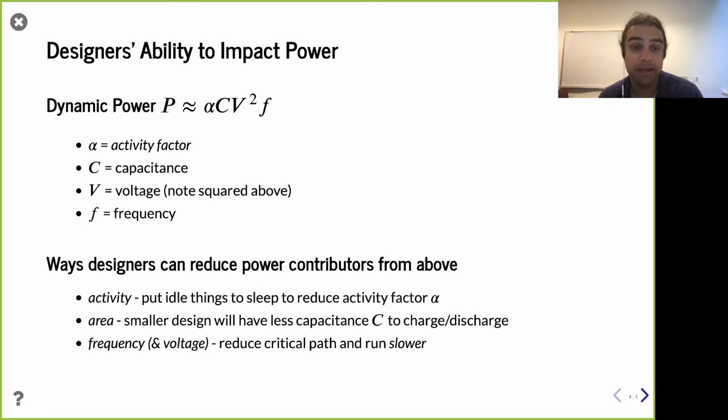And actually, well, the lowest bit of that counter does toggle every cycle, right? Remember, counting in binary, 0, 1, 0, 1, the lowest bit, but then it waits a while before the next bit. So each bit you go up in significance, it's going to flip half as often, right? And so it turns out that many of those bits, if you look at them individually, are also going to have pretty low activity factors.